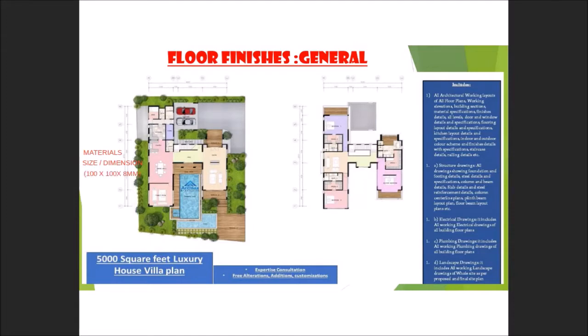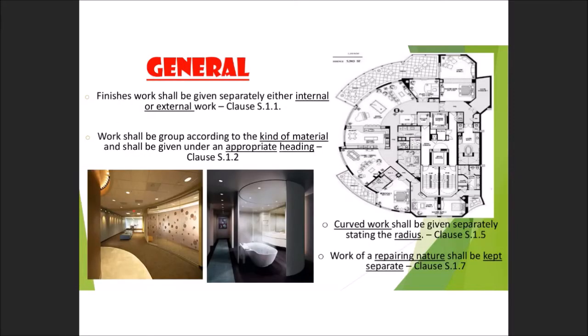And then you may need to see the bedding details. Bedding details means where you want to put the tiles, whether on a 20 mm thick cement screed or maybe 25 and so on. So these are the basic material and specification that need to be identified by the QS in order to start the measurement. This is only the overview.